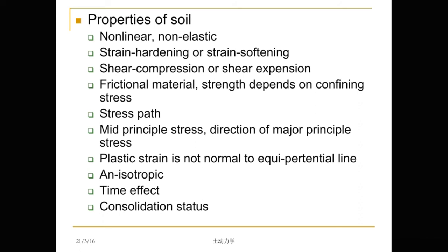They are all principal stresses if we only apply the normal stress on the surface of this cubic body element of soil. Then the middle principal stress will affect the behavior of the soil.